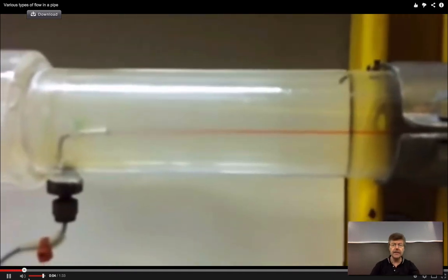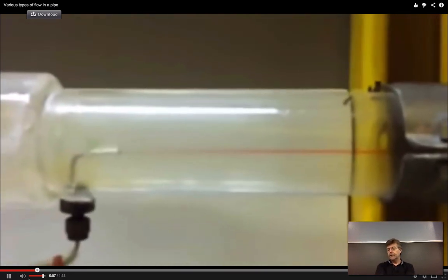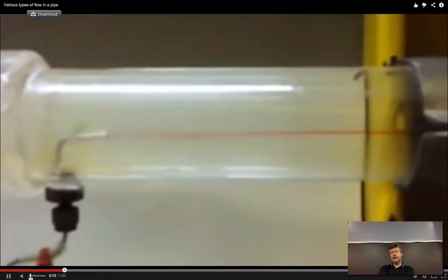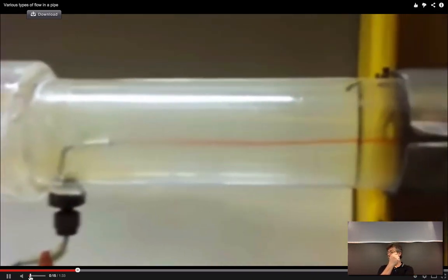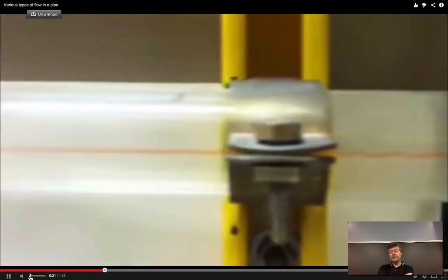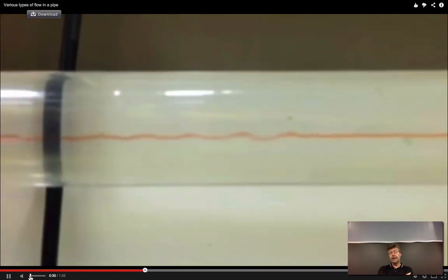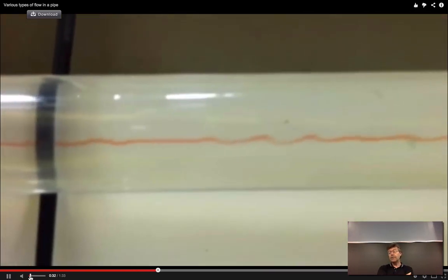So one of the underlying tenets of fluid flow has been that we can represent behavior if we satisfy these three requirements of dimensionality. So similitude. So it has to be geometrically similar. So if you do experiments on a pipe and want it to represent a different size pipe, then it has to satisfy the geometric requirements. And basically our geometric requirements are going to be the length of the pipe to the diameter ratio is one characteristic non-dimensional group, and also the relative roughness on the edge of the pipe, which would be,